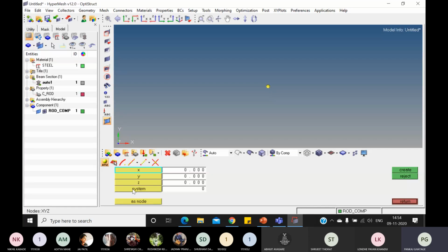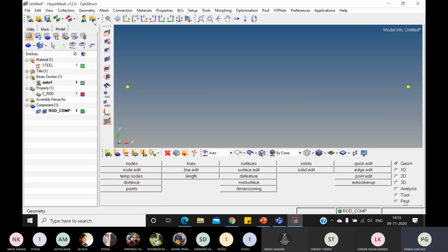Okay. Now second in x direction 500 mm because length is 500. So create and then again put it in. So two nodes will be created. So nodes are created here. Then go to the return. Then we have to give the element over there.